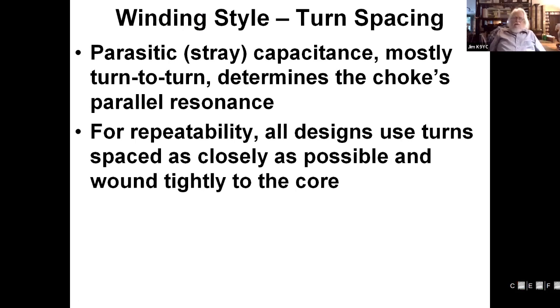We also settled on a winding style of very close spacing so that we could maintain the best uniformity or consistency of turn-to-turn capacitance, which is mainly what establishes the resonance.